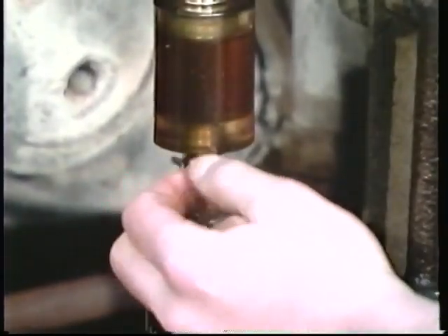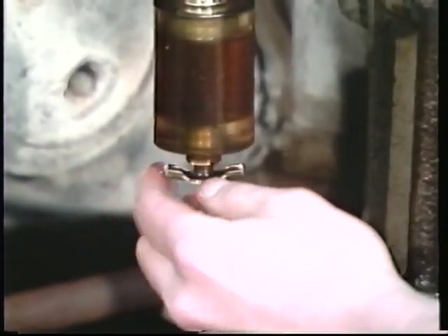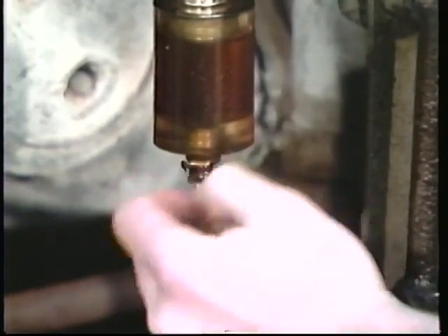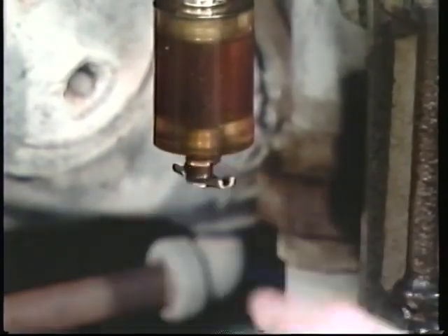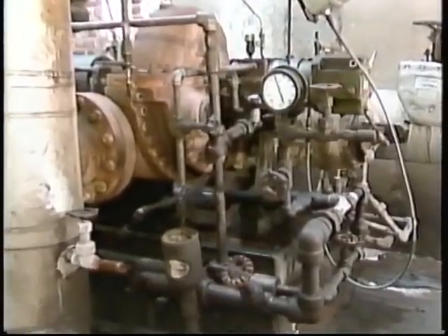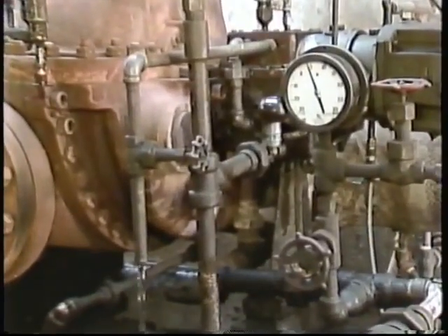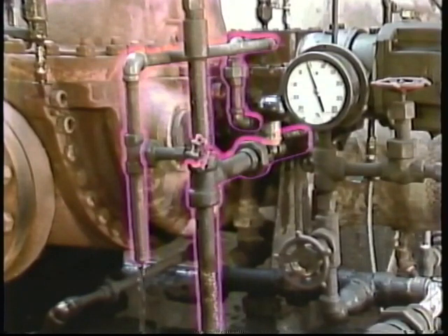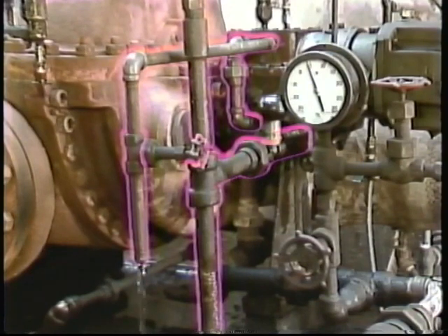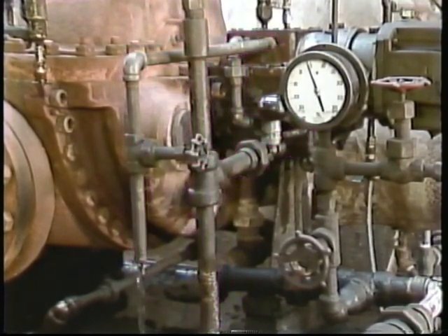Oil that's foamy, dirty, or looks milky, which can indicate there's water in the oil, will probably need to be replaced. To keep the lube oil cool, you may need to put a cooling water system into service. For the turbine shown here, the cooling water is kept circulating through the jackets and the bearing housings even when the turbine isn't operating.